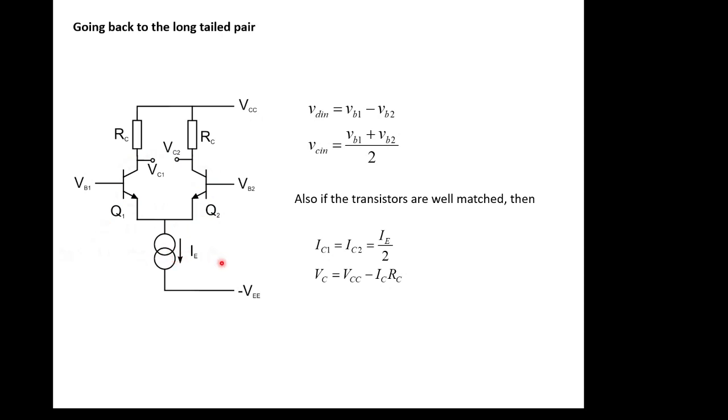The holy grail of integrated circuit design is to make all your devices, all the transistors that you've made onto a chip, absolutely identical, because then all this maths becomes ideal and wonderful. And that's why it's hard to make a well-matched amplifier from transistors that you get out of the drawer in the lab, for example. First of all, they've all come off different substrates because they've all been chopped up and mixed in the box. So they'll all be slightly different in terms of their GM or their various currents or their voltages. And also, if you put them onto a circuit board, there's a good chance they're going to be seeing different temperatures. Even small temperature gradients can make a difference.